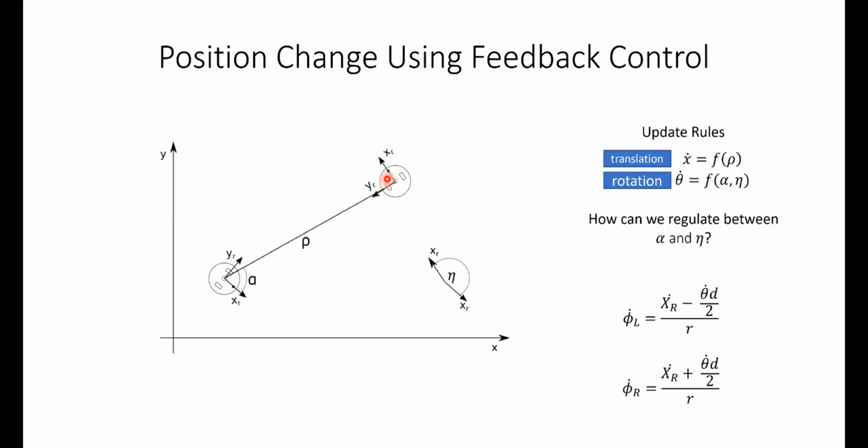And the length of that arc is going to be greater than just the straight line distance between those two points. And it turns out that that's okay. Our translation will be wrong in that it won't accurately reflect the total distance that the robot is actually traversing over the course of that whole path. But the fact that we compute it every single time step means that it's converging towards the correct behavior, because eventually our rotation will zero out, and then we will only be driving forwards. And so those things will become equal.